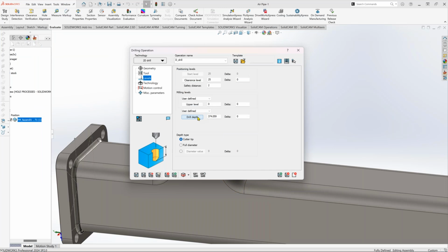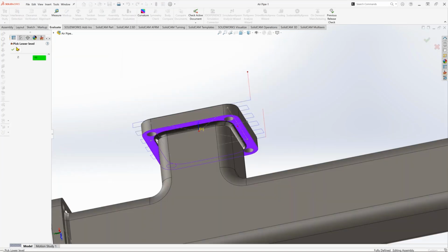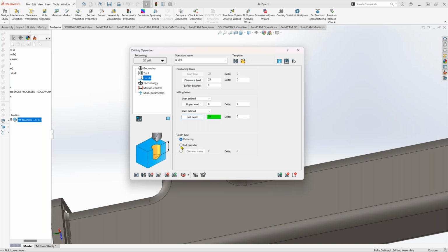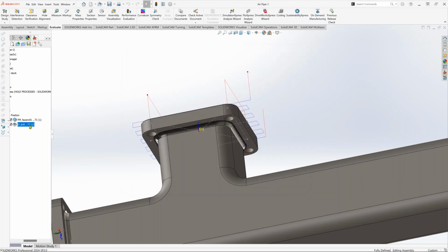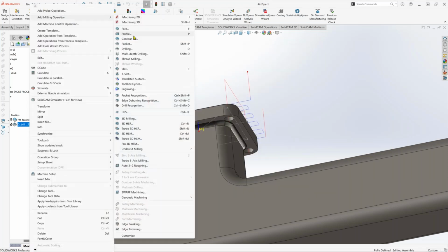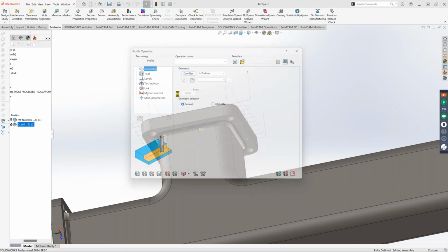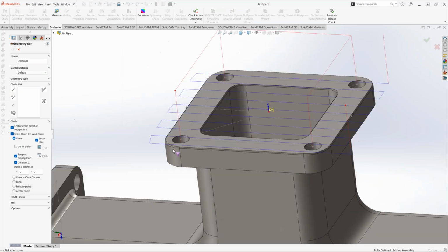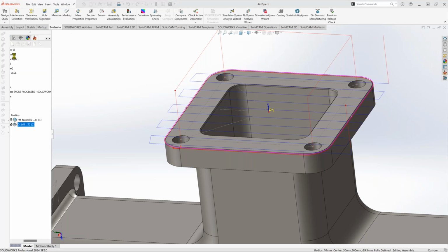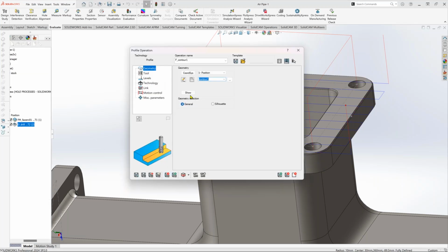And let's make a depth of the drill. Just go out here, make a full diameter, and just ensure it goes out about half millimeter additional. Okay, and the profile around. I'm not going to make a canvas and things like this, just to show how it works. Okay, so the profile. I will use the same 12 mm mill, okay, to machine it.